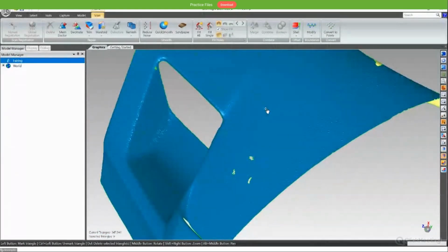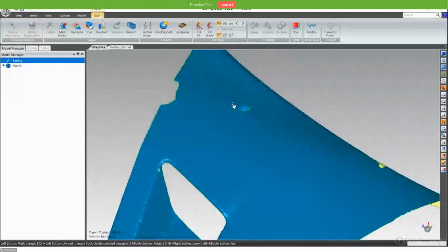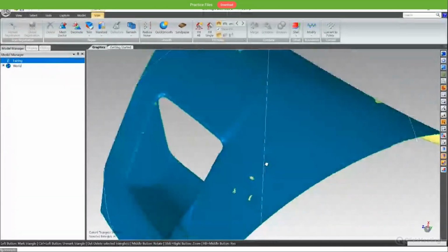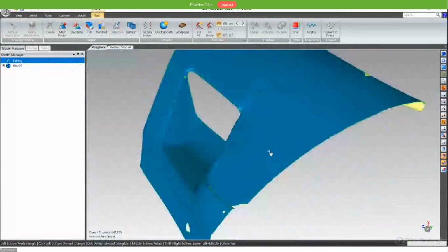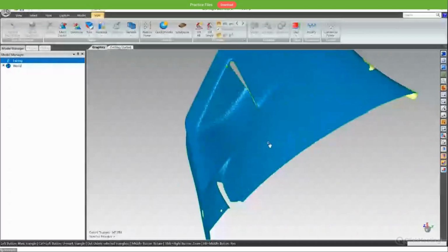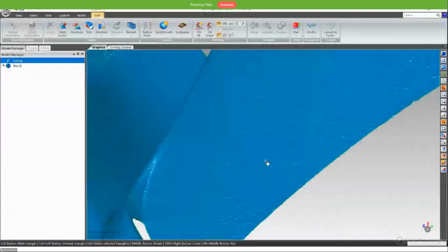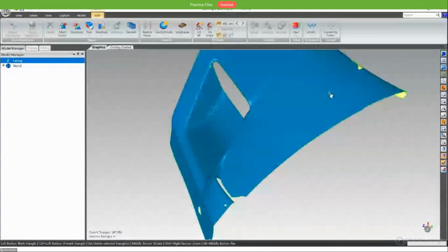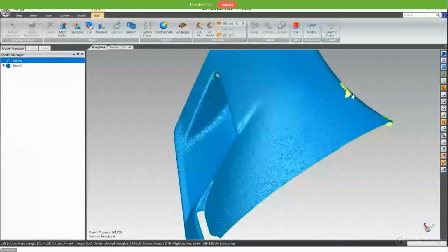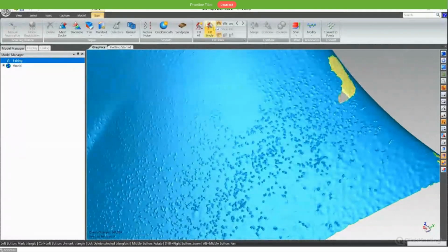It's not only able to delete some parts like this, it can also fill holes. Like here, we have three holes, and some holes are also kind of a feature of the scan model, and you select them and also run the defeature, and the holes will be filled. But the difference between filling holes using defeature or filling holes here is in some areas like this, where we have some curvature, the fill holes function will process much better.